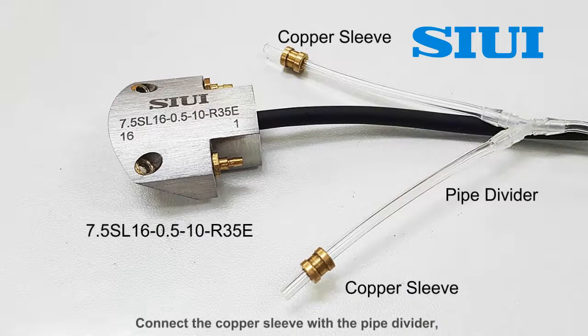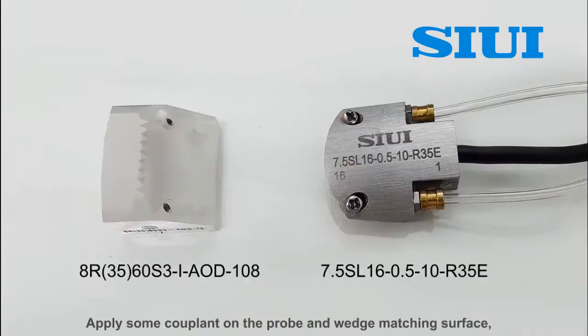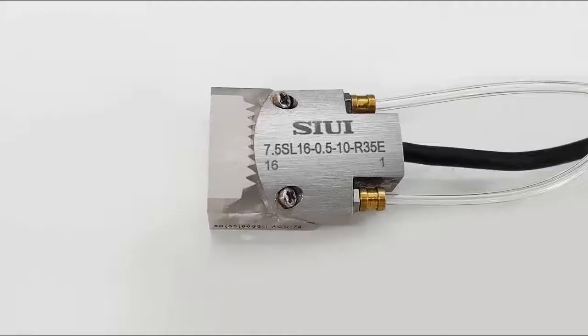Part 3. Probe and wedge assembly. Connect the copper sleeve with the pipe divider and insert the pipe divider to the probe irrigation column. Then insert the copper sleeve in the irrigation column firmly to fix the pipe divider. Apply some couplant on the probe and wedge matching surface, and assemble the probe on the wedge with a cross screwdriver.